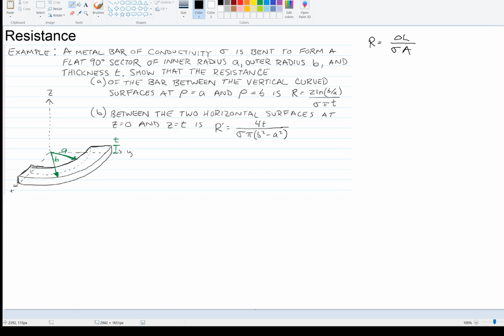So when we say uniform conductor, what we mean is that the cross-sectional area of the conductor, A, I guess we used S in the video. Let me use S. We mean the cross-sectional area S is uniform, so wherever you slice it along the length, it's going to be the same anywhere along the length. And it's got uniform conductivity, meaning the material is homogeneous. It's carbon, for example. Carbon would have a conductivity that we can look up in a table. So we can use this equation.